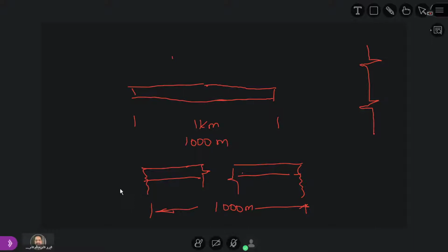Okay, this is the component and this is the size. If I give you both in dark lines, then you'll be confused about which one is the component and which is the dimension line, right? So that's why we make the actual component in a thick line, and all the remaining dimensions in a thin line, right?